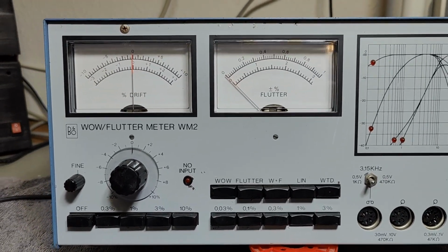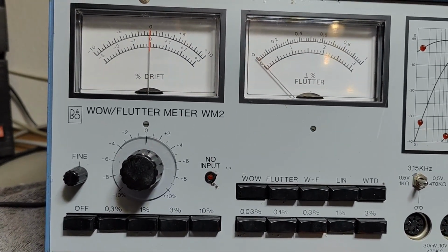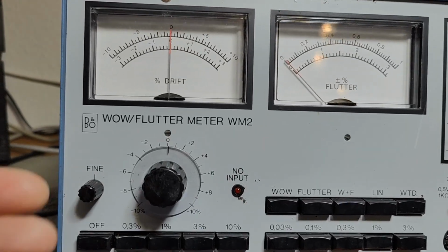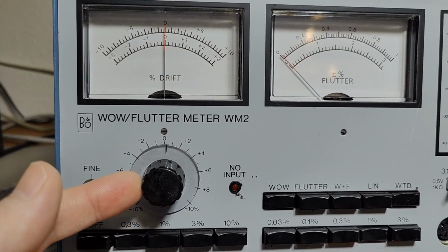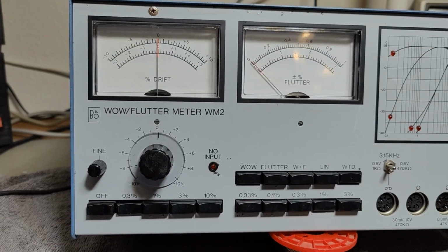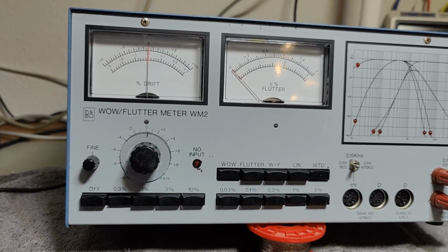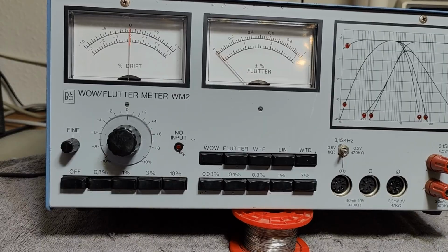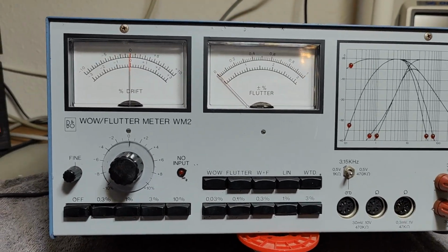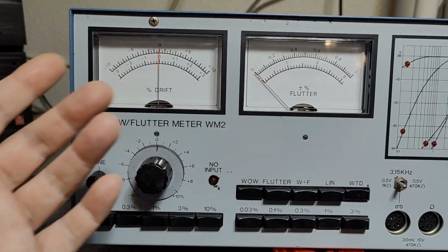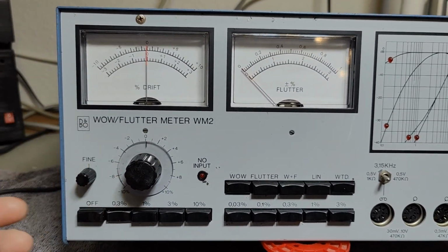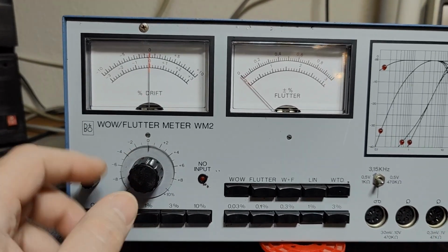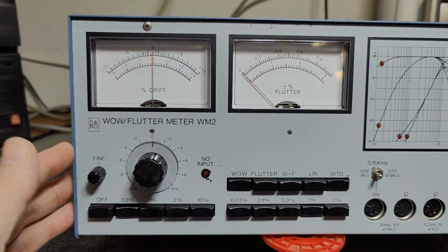So what is the difference between these three things? That is the frequency of the variations. So drift is like a constant offset. Let's imagine the tape recorder is running a little bit too slow when it's recording and a little bit too fast when it's in playback mode. That means the output frequency is different from the recorded frequency, and that is your drift. Drift can be from constant and up to about a half a hertz or something like that. Very slow drifting, like an offset or an error, constant error.